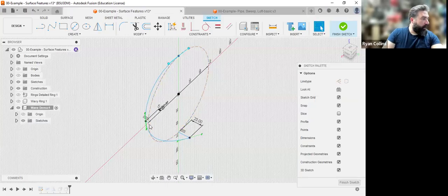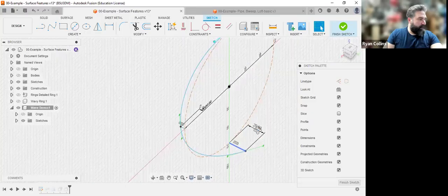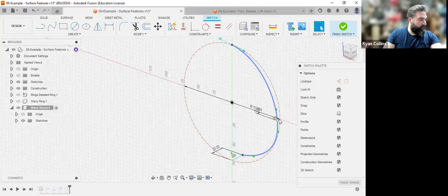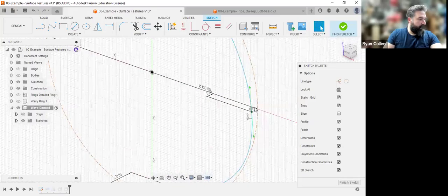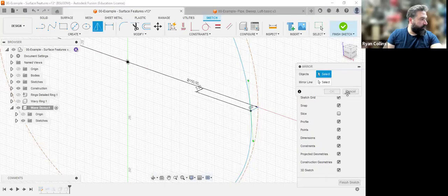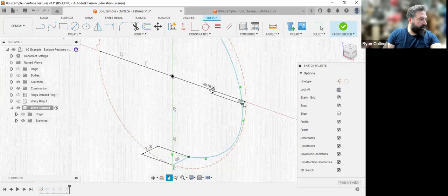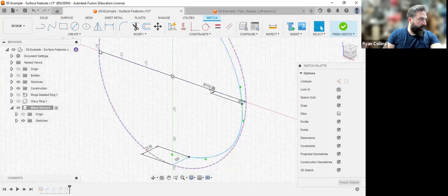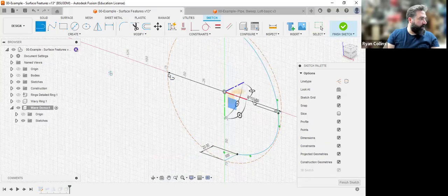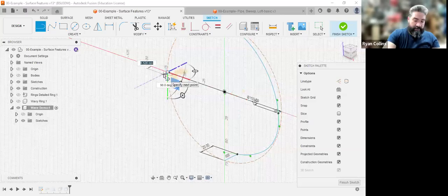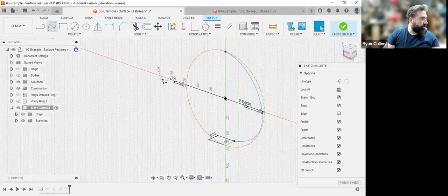Huh. Okay. Well, easy enough, since right now it is just this one other extension point. No problem. So let's just duplicate that one. Yep, can't do 3D. Okay. So that means I can either just draw a line over here directly, or I could use a circle pattern, make just one. So since it's just this one point, it's only 5 millimeters out, let's just make a copy of that. So a line on the other side, it's going to be 5 mm out. There we go. Okay. So do another fit point spline.